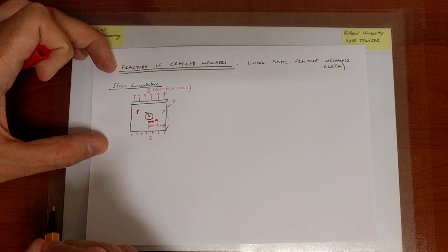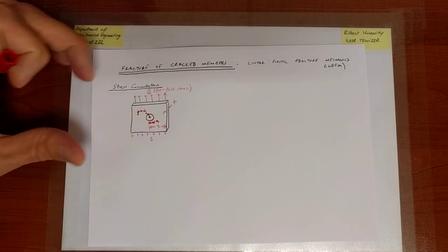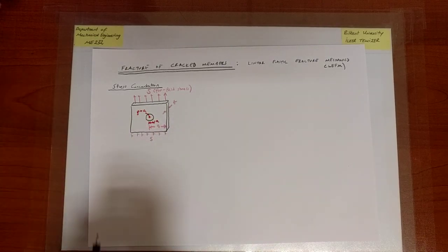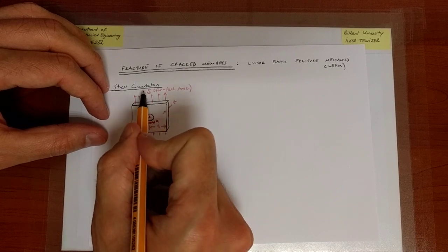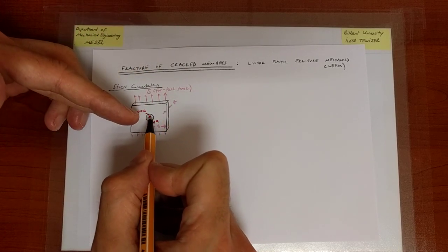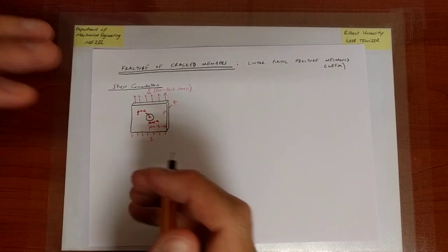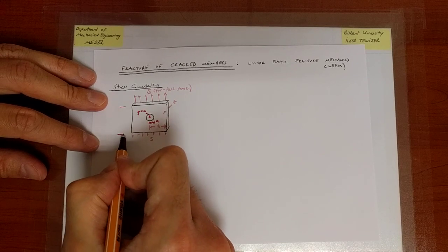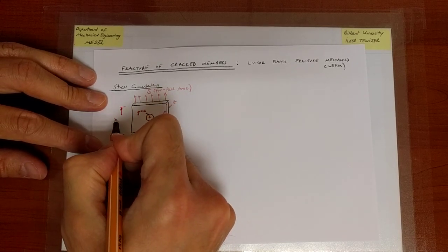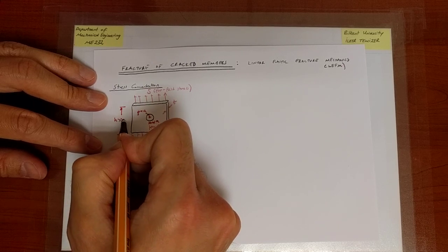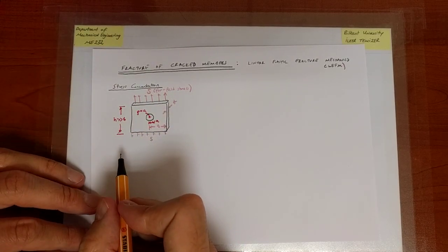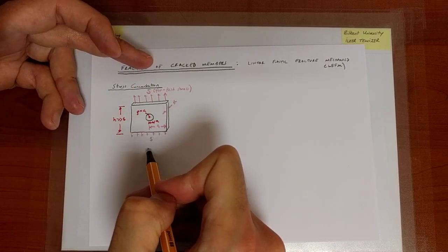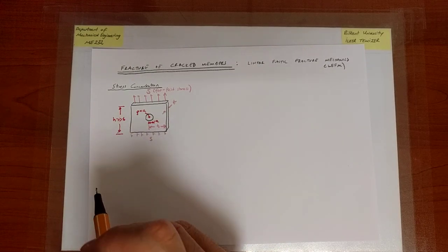That's a typical way to indicate the radius, and the radius is A. Okay, so the half width of the hole is A, the radius is also A. Now, we want the upper surface to be sufficiently far from the position of the hole so that the stress field is uniform. So we are going to somehow enforce that through the condition that the height of the plate is sufficiently large compared to the half width. So in other words, the hole is relatively small in comparison to the height of this plate.